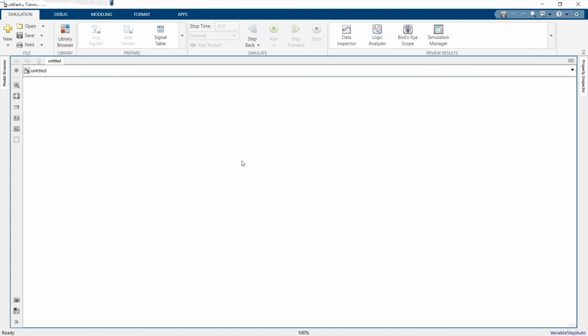Now all the ports are on the same side. In order to change the side of the port, what you have to do is double click, and port location is left, change it to right. Now my ports are at their required locations.